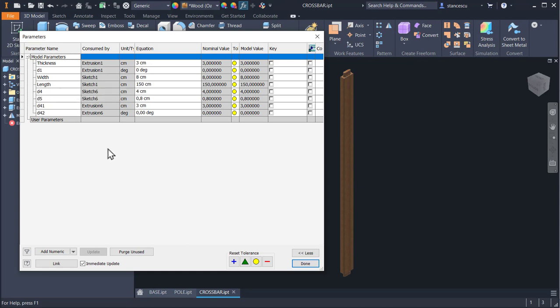What you have to know is that the values of these three parameters come from the assembly to the component. You cannot write here any expression by thinking that the expression would be calculated in this procedure, general procedure with iLogic.